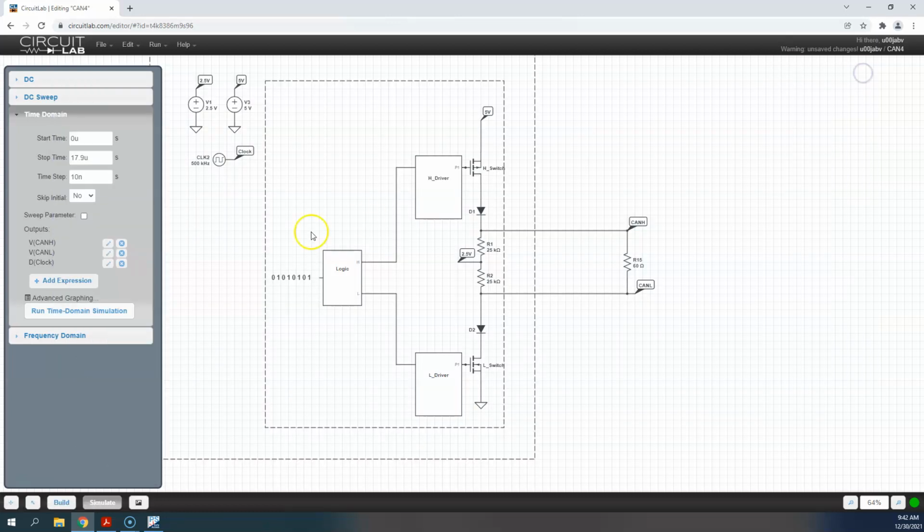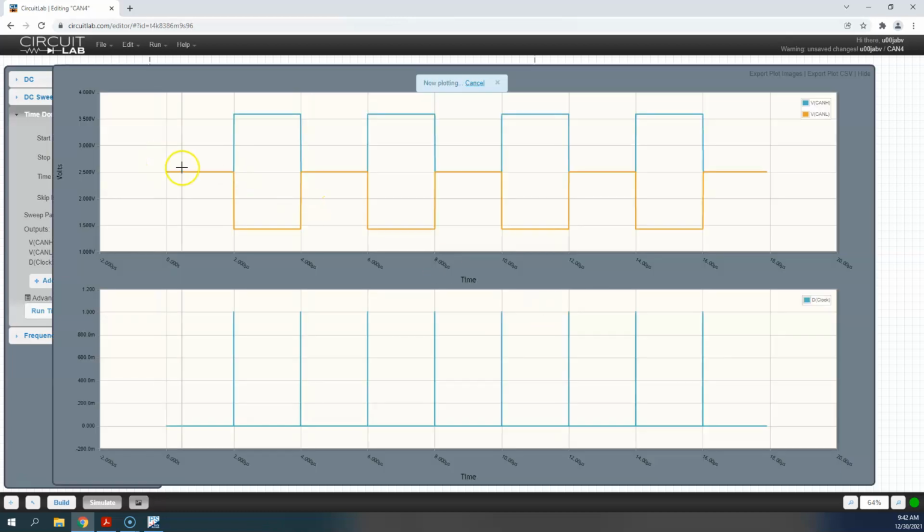So this is the CAN transceiver acting as a transmitter. It's putting information out onto the CAN bus. One of the things that's very important is that the CAN bus has to be quiet before we do that. So at this point, this isn't really what we would call a logic 1. This is just the bus being idle, and the bus has to be idle and quiet for some period of time before any controller can come in and transmit this first bit to start the frame and say, hey, I want to take the bus and I want to put a message out on the bus.